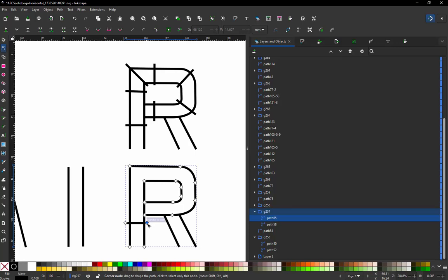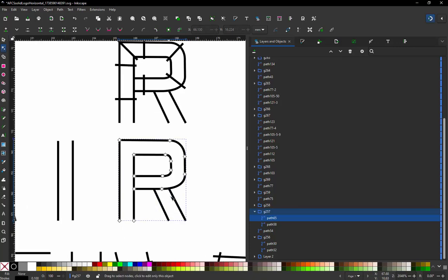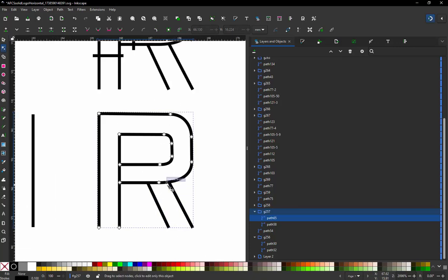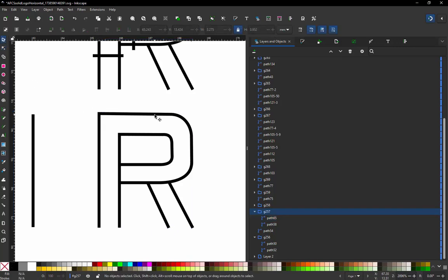Now, one thing to point out here, when we don't have rungs, we do have to have matched node pairs to define our stitch angles. So for example, we have a match, a match, a match, a match, and a match. So in other words, we don't need rungs. That will take care of it.